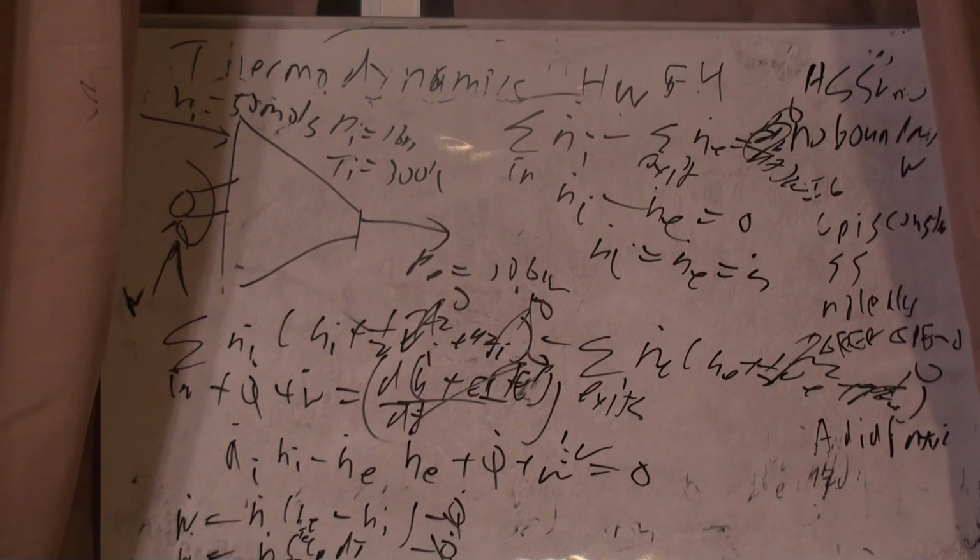Now, is that realistic? Obviously not. So I probably cannot assume an ideal gas in this case, and I should probably use some other equation of state. Even a van der Waals would be a better estimate than an ideal gas. But technically, the minimum amount of work would be 0 in this case because it's adiabatic.